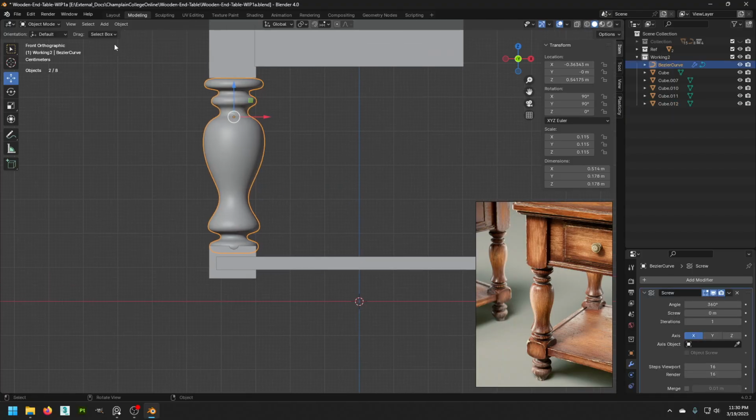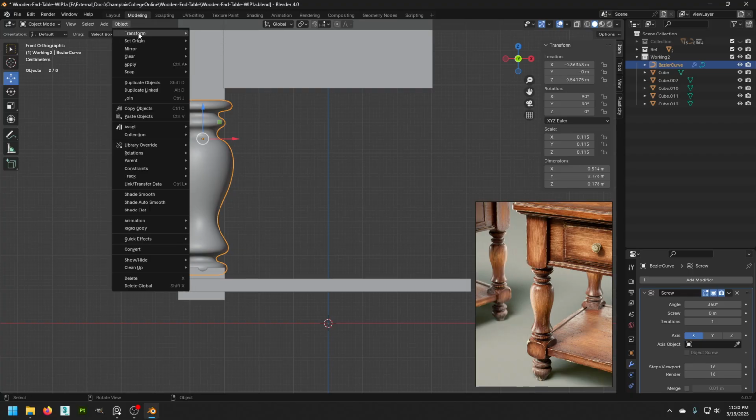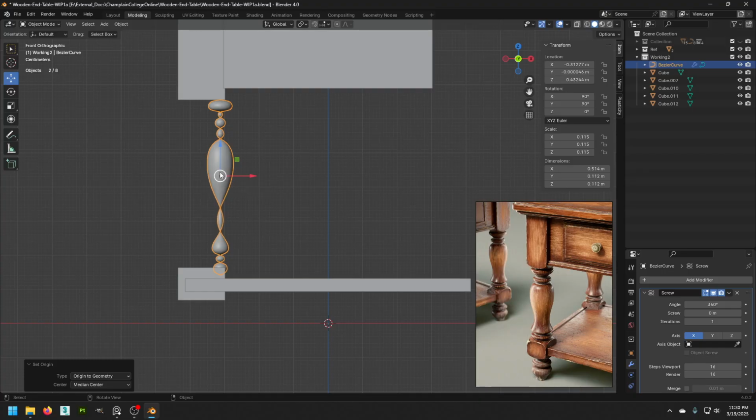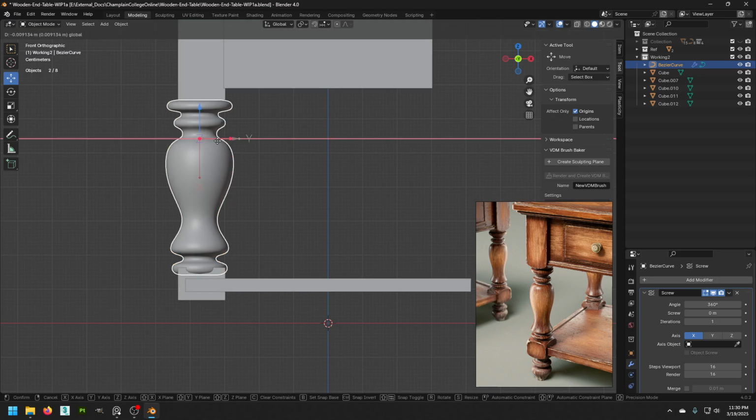Okay. So let's go and adjust the pivot point on this. So you could set the pivot to be the center of the geometry, but what it does is that it brings it outside of that. So we actually need to affect our pivot a different way. So if we go over here to this tab here, there are different tabs here. And you have the origin. This will be able to affect your origin.